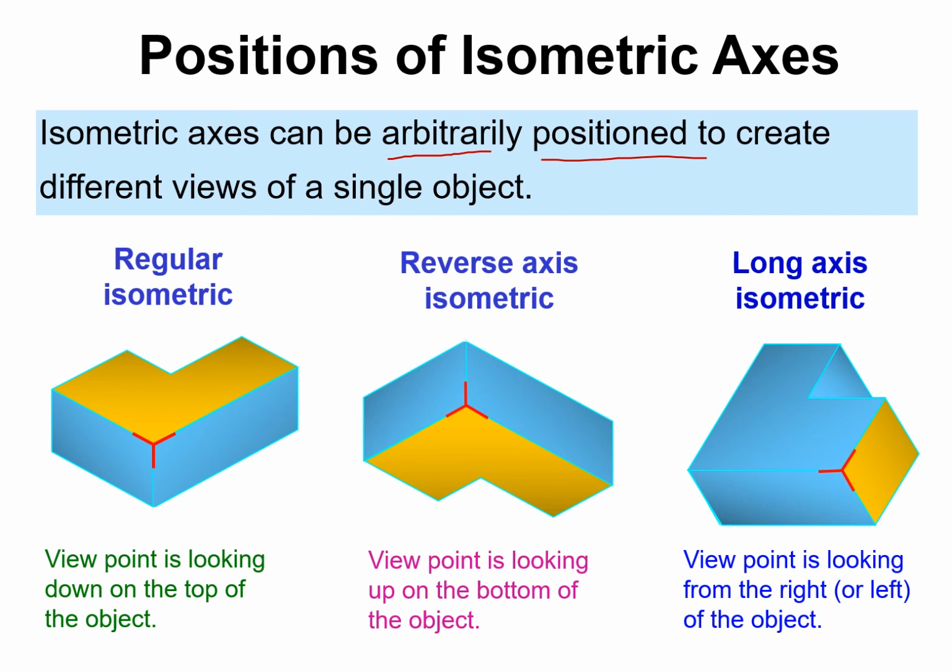Just like in regular isometric, we look from the top at a certain object. The edges that are visible, the corner that is nearer to us, and the three edges that define this particular corner, we take those three edges as our axonometric axes. We then define the angle between these three axes, and then we identify them as isometric, dimetric, or trimetric.